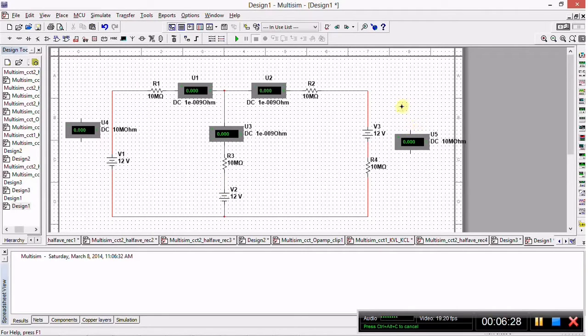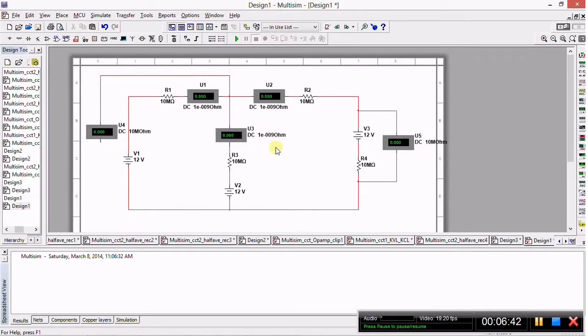So I'll connect this voltmeter in parallel across what we consider the battery, which is this power supply as well as the resistor. And then connect this across the terminals X and Y.